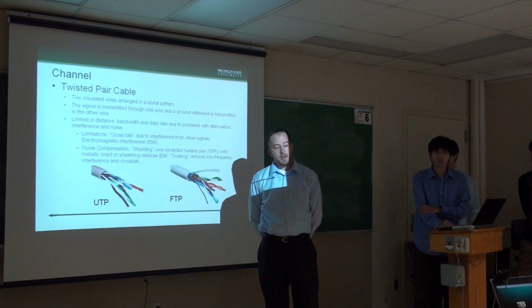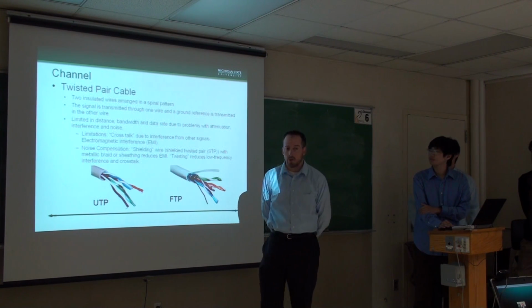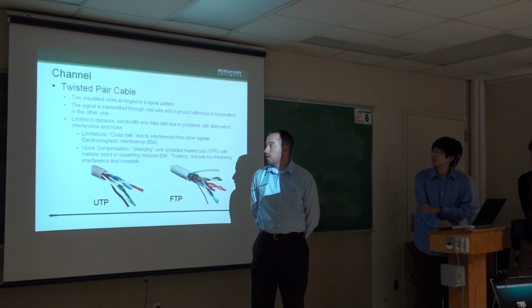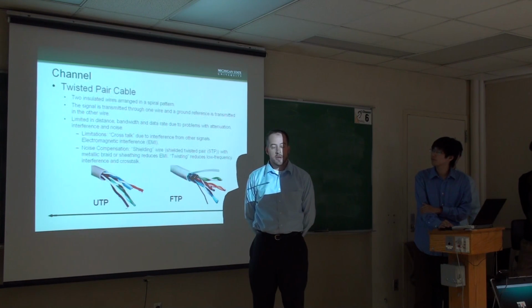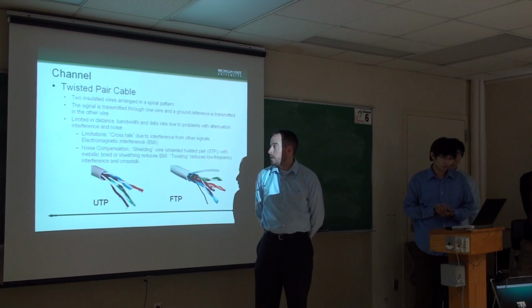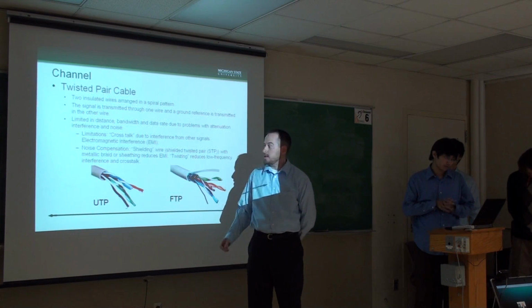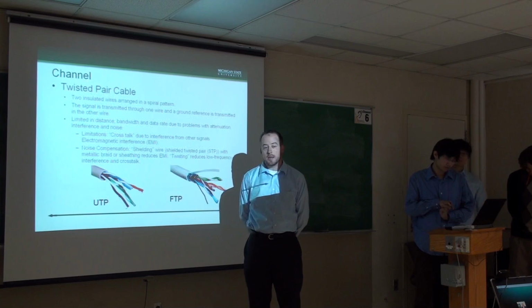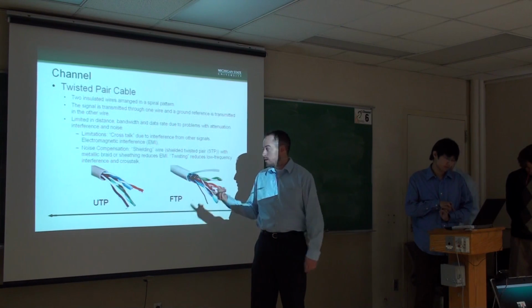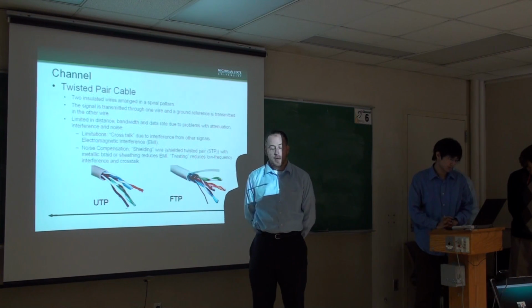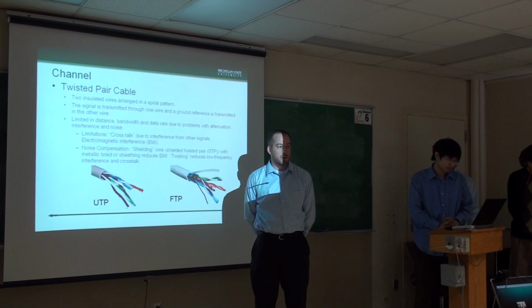We've already talked to our sponsor, and according to the electricians, they have a lot of twisted pair wire available for transmission from the transducers. There are risks in using it, such as if it is subject to attenuation at high data rates. But essentially, if you're using twisted pair, it's going to eliminate crosstalk between the channels.